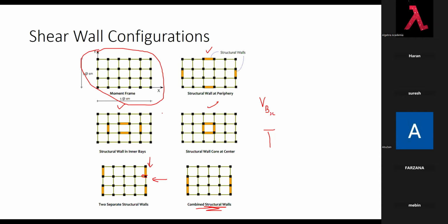And mostly what they found is that this kind is the best. This gives better results. Again, the problem here is that there is a small gap. Because of this gap, this beam will be subjected to more secondary force. So most probably they will prefer this one. Otherwise here they have to go for a thicker beam from the torsional point of view. So in this case this will not come. It is like a fully rigid member. It takes however much torsional value is coming, and based upon that they give the reinforcement.